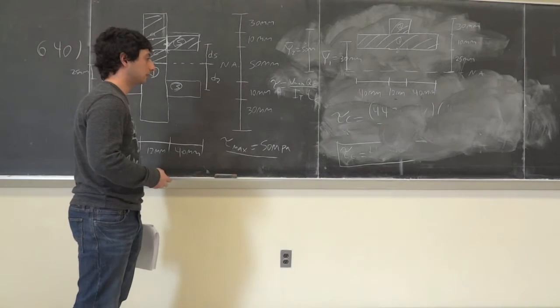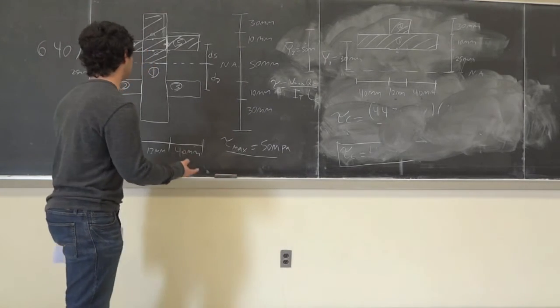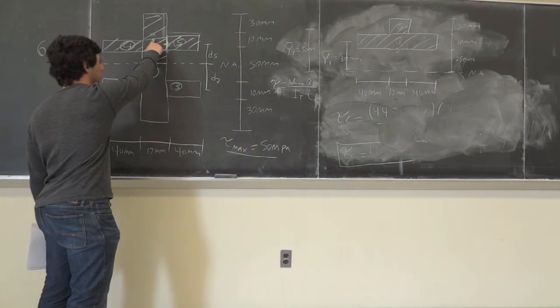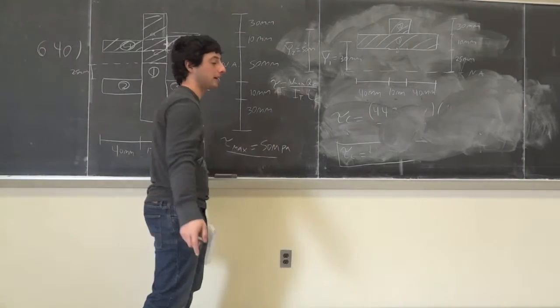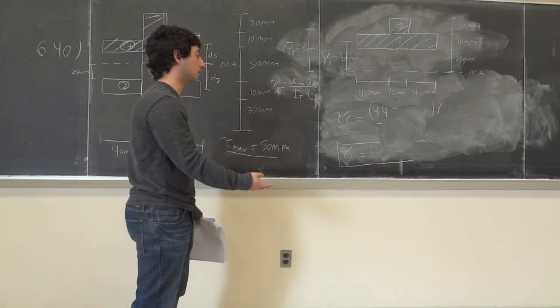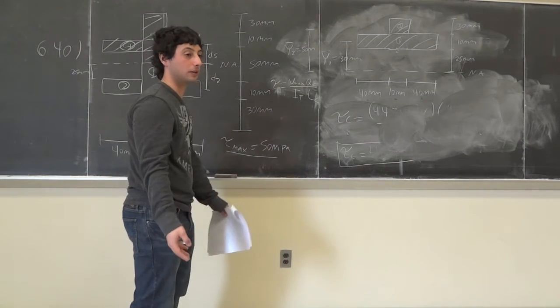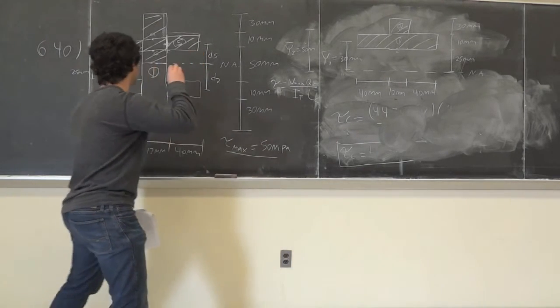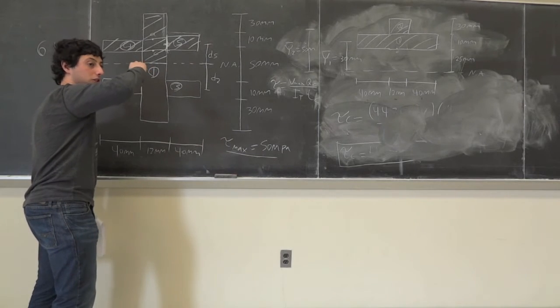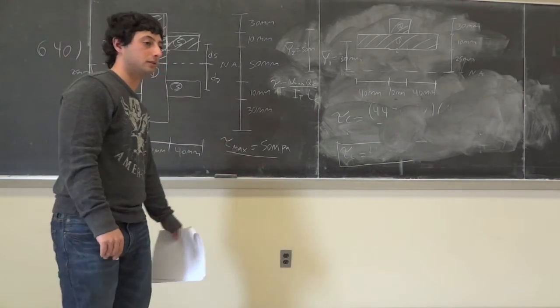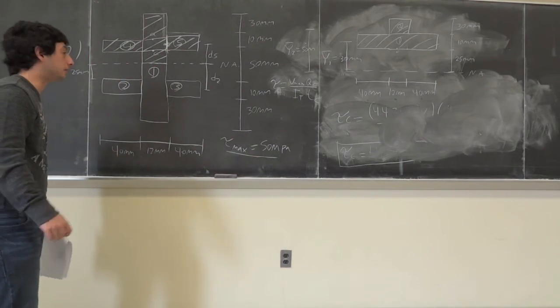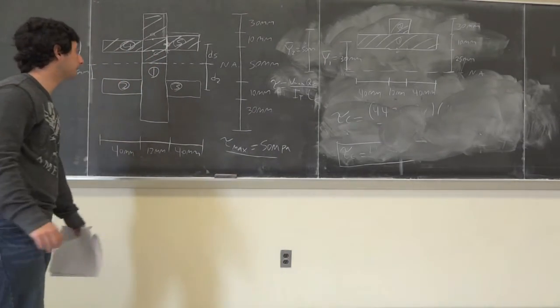You need that in order to solve for the transverse shear in these sections, because remember, this formula is VQ over IT. So you need V in order to solve for each one, and they don't give it to you. V is a transverse shear force. If that's a cross section, the shear force V would be vertical? Yeah, it's vertical.